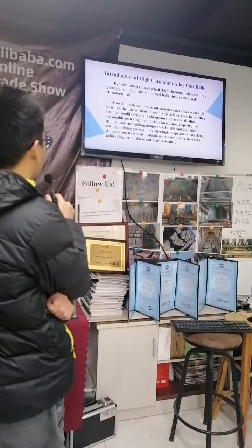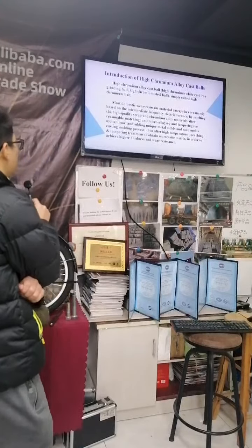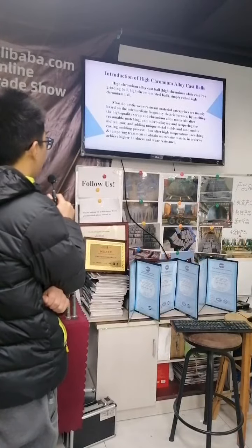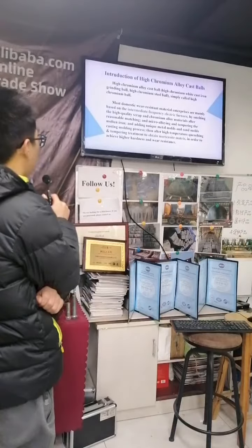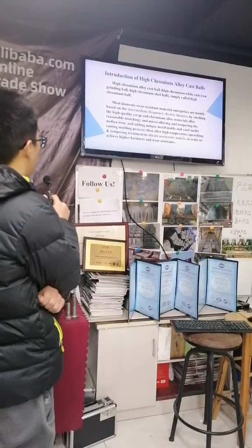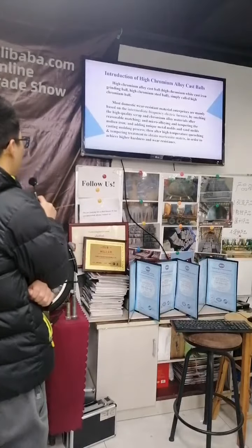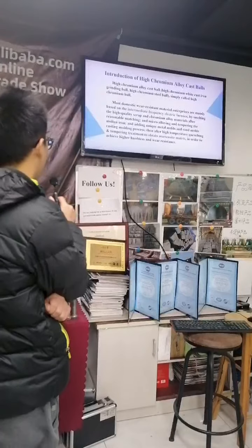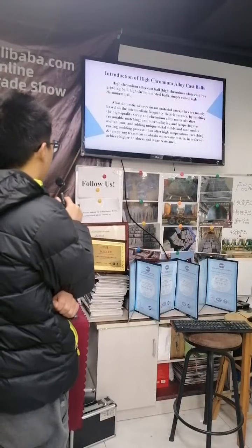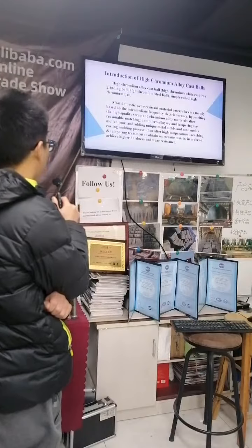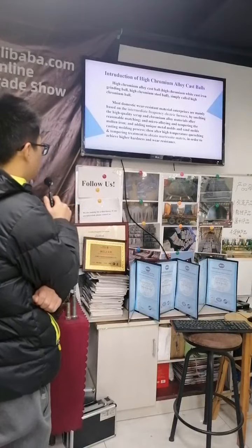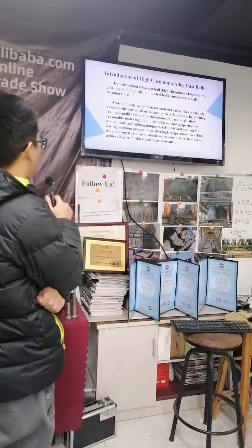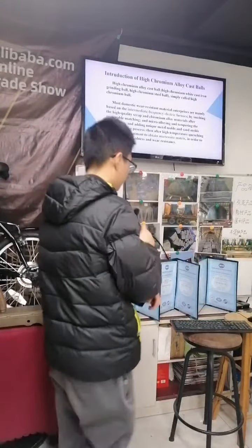Most domestic wear-resistant materials and devices are mainly based on intermediate frequency electric furnaces. After adding high-quality scrap and chromium alloy materials, with reasonable matching and micro alloying and tempering of the molten iron, and adding unique metal molds and sand molds in the casting molding process, and after high temperature quenching and tempering treatment, it can obtain the required metrics to achieve higher hardness and wear resistance.